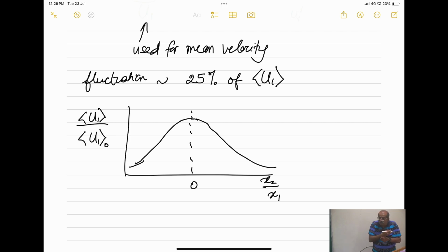So you have to carry out a much larger number of calculations. And this is why, when you do turbulence modeling, you say that I will only solve the equation for mean velocity. I will not solve for fluctuations at all. And then you are in a better state, the mean velocity is smooth, so you can have bigger domains. Okay? Does everybody see that?